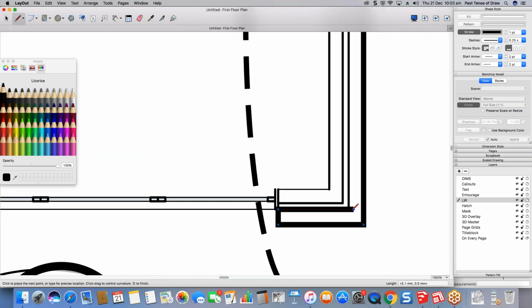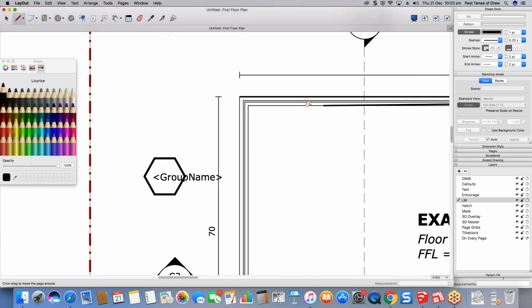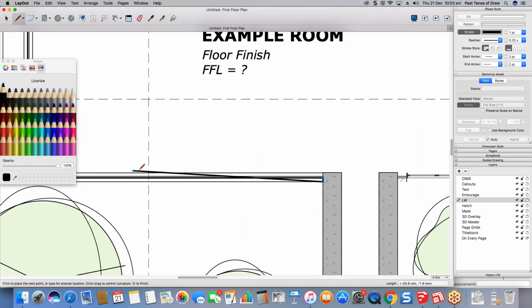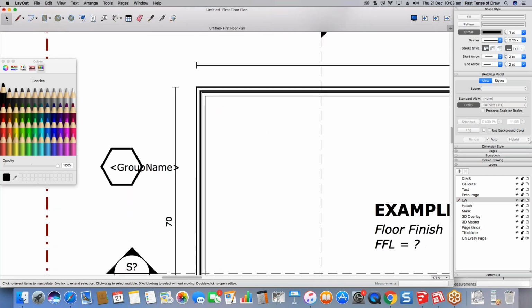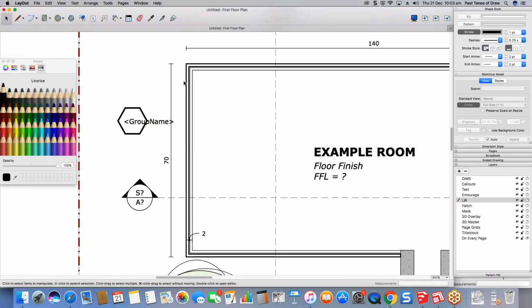I could even go around doing the cavity itself. It's a very quick process. It doesn't take very long at all, but it gives me a lot of ability to represent it how I want. And this is what you're doing in AutoCAD regardless. And if you're doing it in any other third-party software, typically you're going to that degree or that level also. Best part is, if you do change your model, it's very easy for you to manipulate these custom line work layers as well, because you can either hide them, you can put them back on, you can grab them, and you can control them separately. So if I knew that this needed to move out, I can grab it, I can grab this one, I can do it via scale and via distance too, like so.